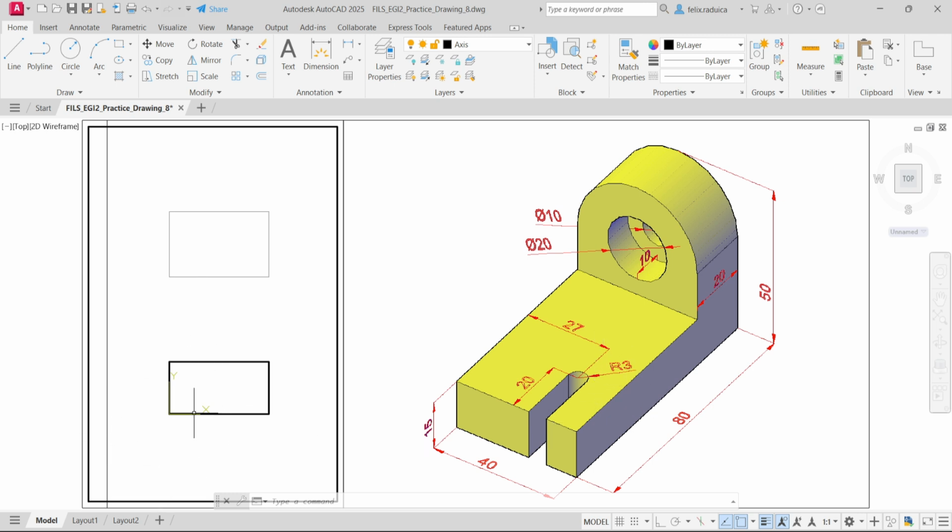So if I have my coordinate system positioned here, I want to create an axis which is 20 millimeters, add in the 3 for the radius, and then the extra 3 millimeters to the right and 3 millimeters to the left, so that we have the whole axis line.